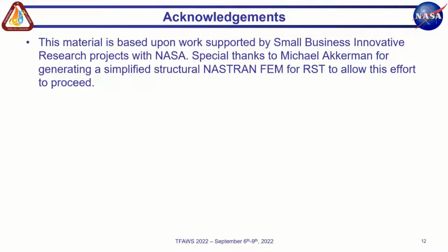Our next question, would there be any assumptions such as linear, small deformations, etc., while creating a reduced order model? Really, whatever assumptions you're making for the high fidelity model, whether that's the Nastran model or the thermal desktop model.